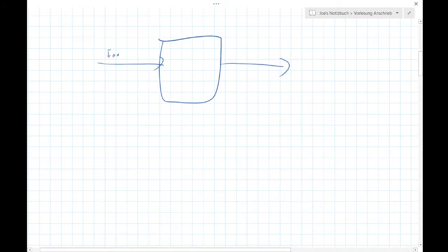Also for yields, you will need to do mass balances in such a system to know what is happening there. So it's a reactor, a feed stream, and the product. In the feed you have just glucose, and you have 10 grams glucose. In the product stream you have 4 grams fructose, and 0.5 grams mannose. And you already see by eye that you also need to have glucose. So you have also glucose.